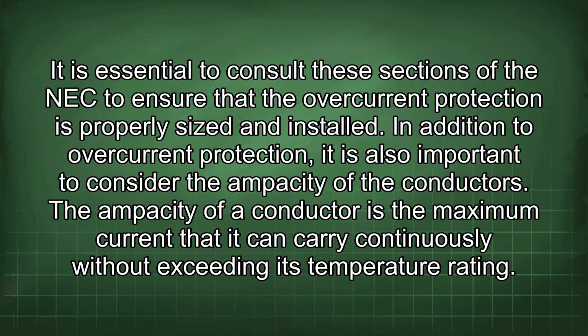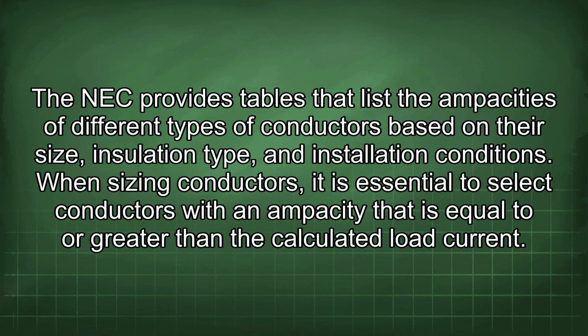It is essential to consult these sections of the NEC to ensure that the overcurrent protection is properly sized and installed. In addition to overcurrent protection, it is also important to consider the ampacity of the conductors. The ampacity of a conductor is the maximum current that it can carry continuously without exceeding its temperature rating. The NEC provides tables that list the ampacities of different types of conductors based on their size, insulation type, and